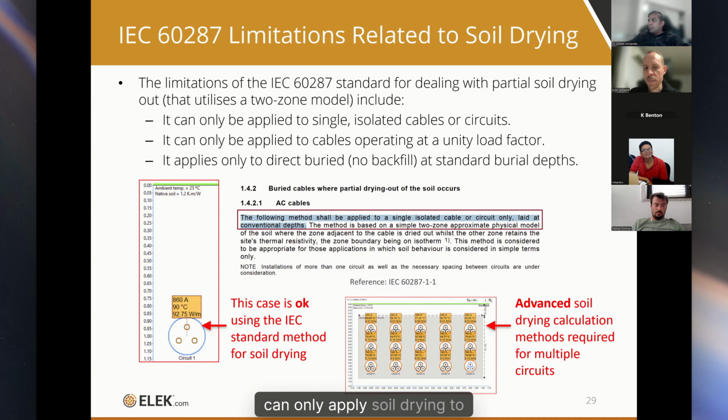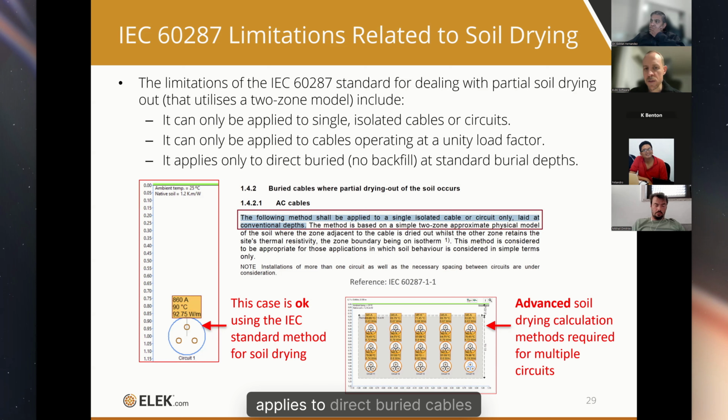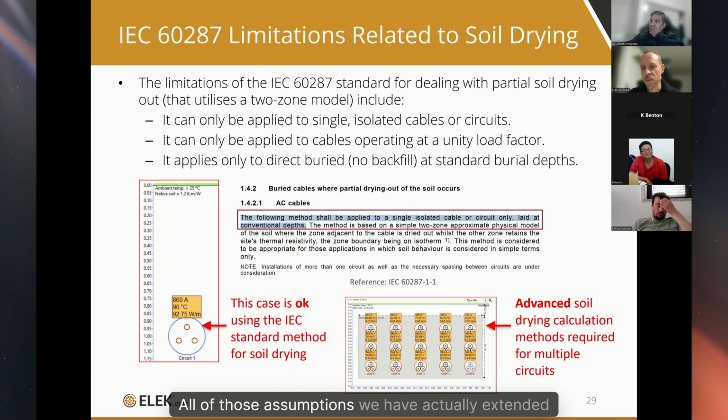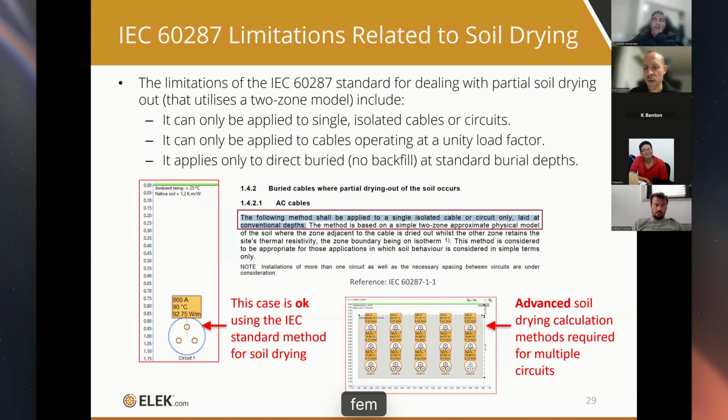Also, you can only apply soil drying to unity load factor. We don't have that limitation either. And it only applies to direct buried cables at standard burial depths. All of those assumptions, we have actually extended those limitations, but in general, they are a limitation, and there are more considerations. A different approach is required for FEM.